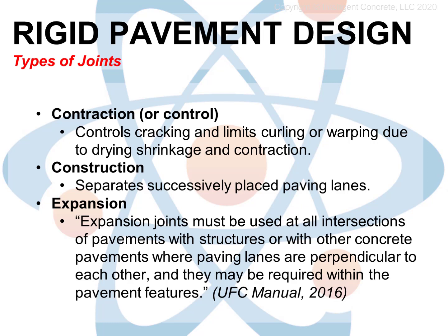Cracks will occur as a function of the concrete curing. They are unavoidable in any pavement larger than about 20 feet or so in either direction. As the water in the concrete mix is used up by the process of hydration or curing, the concrete shrinks a little bit. A small pavement, say a little patio behind your house, might not shrink enough to need any joints. But as concrete cures, it can shrink as much as a half an inch or more in 100 feet.